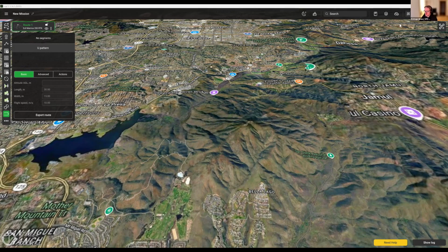Now you might ask, how are they doing it? How are they planning these missions for a Mini 5? It can work in the following way. It's a bit of a workaround, and a bit unofficial, but you can plan just a simple waypoint flight on the DJI app, right? And when you do that, a KMZ route file gets saved on the controller. So what you can do is plan a mission within UgCS for, let's say, the Mini 4 Pro drone. Then you can export this route into a KMZ file, and then you can simply replace the file that's on the controller.